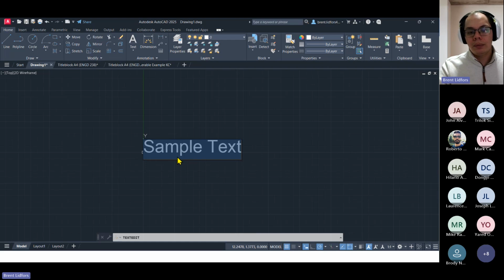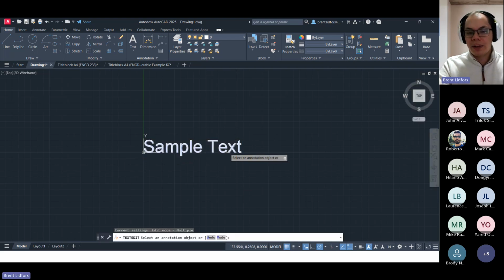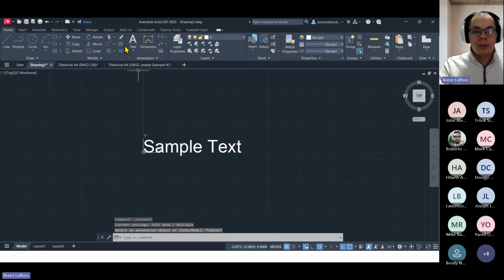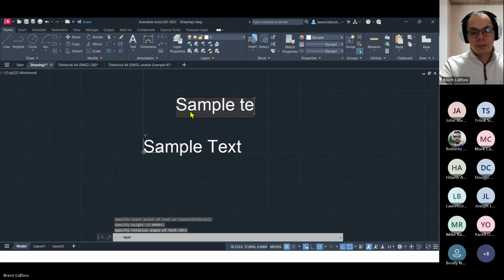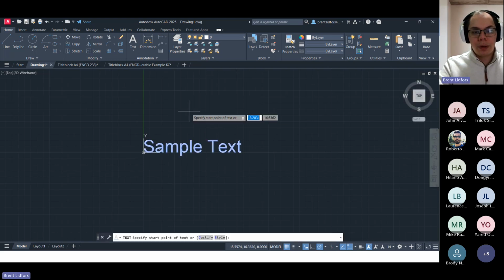I have to go back in here and change that if I've already set the text, or during the process of making single line text here, or I've already skipped it. It's my bad. I need to hit the down arrow before I start any text and go to justify. Okay. So before starting single line text, I have to justify, whereas multi-line text, it was up in the ribbon.